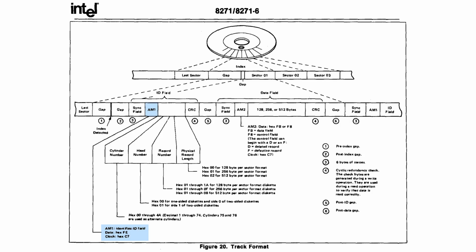And after that address mark, the ID chunk simply contains the track number, the head number, the sector number, and a size code which says how much data is going to be stored in this sector, followed by a CRC that's just used to make sure that there were no read errors when reading that data. And that's the entire content of the ID chunk. It's quite a small thing. And what happens is 17 bytes along the disk later, the drive should find the start of a data chunk.